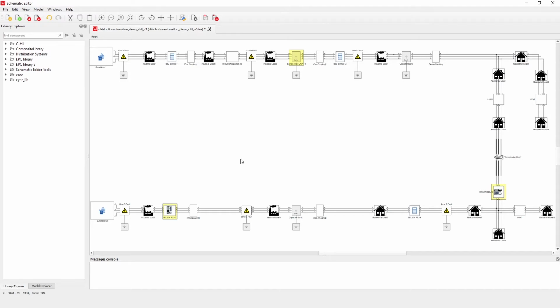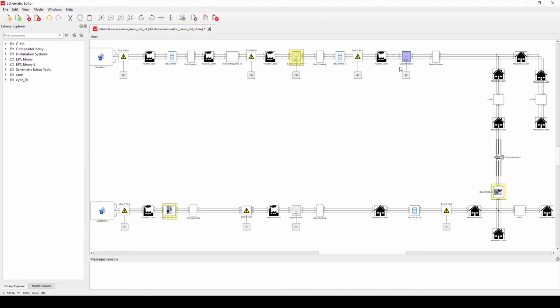Each zone consists of some combination of loads, either classified as industrial or residential, switched capacitor banks, either controlled with an internal signal processing based controller or a hardware controller in the loop. In this case, an SNC IntelliCap 2000 capacitor controller is used, meters, and regulators.